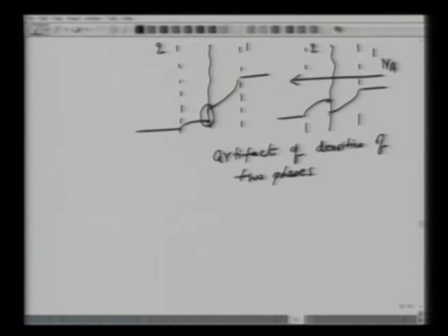Na diffuses like this. Here also it diffuses from right to left. So this doesn't mean that we have a diffusion from lower concentration to higher concentration. More important is what happens within this film here and here. There is a concentration drop from here to here and from here to here. At the interface we have equilibrium.